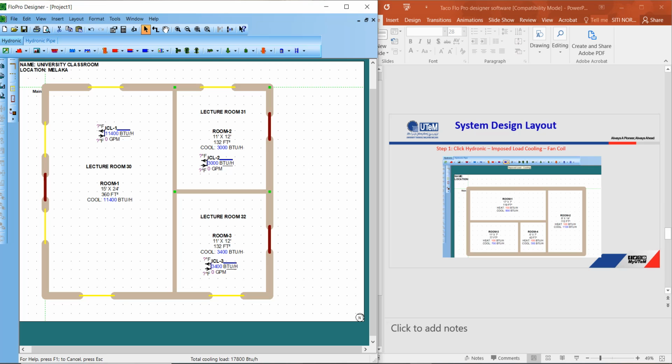So you can do a piping connection using this system. Just select the system. Let's say we use air cool chiller. No manufacturer. Compressor type is screw, centrifugal, just choose what you want. Let's say we choose a reciprocating compressor. Just press this here. And how do we want to connect this piping system? Just use this connect icon.